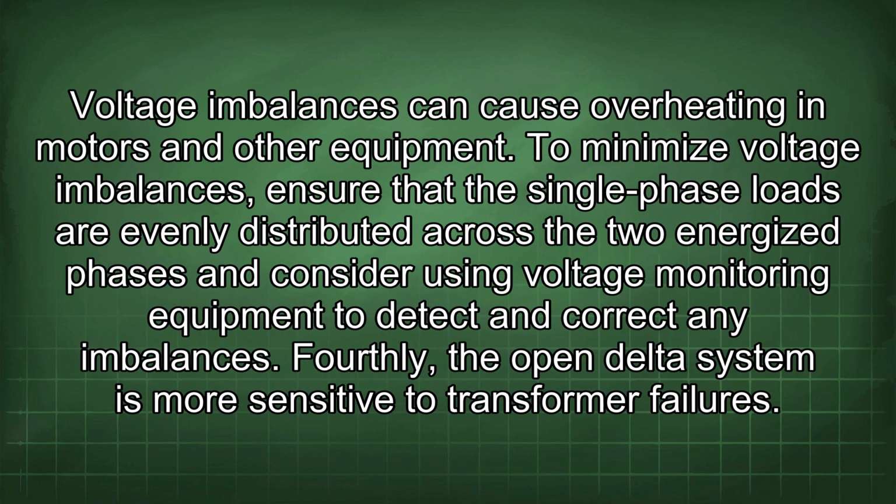Voltage imbalances can cause overheating in motors and other equipment. To minimize voltage imbalances, ensure that the single-phase loads are evenly distributed across the two energized phases and consider using voltage monitoring equipment to detect and correct any imbalances.